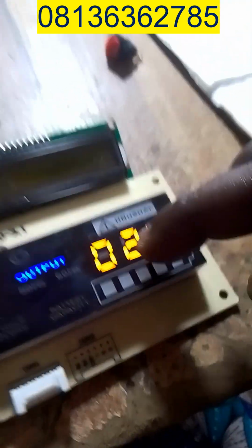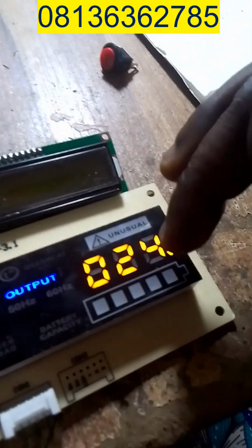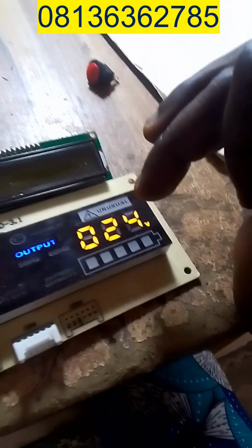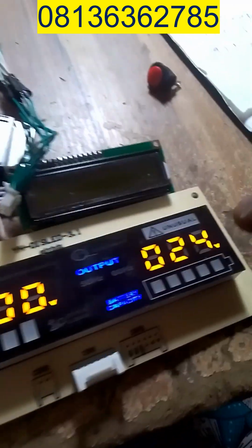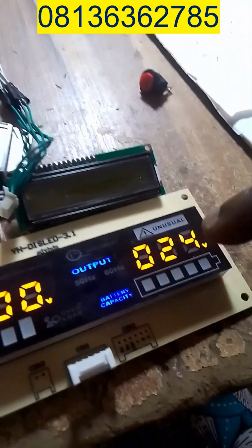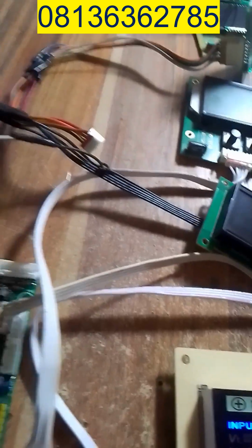Then that's another part. The other part is to change the voltage. For example, presently, during the diagnostic mode, the output of all the displays you selected will display the working voltage that the board will work with after you have exited the diagnostic mode. So for example, now this one is on 24. It means that if I exit the diagnostic mode now and connect the battery, the system must be a 24-volt system. To change the voltage here, you have to press this button again.